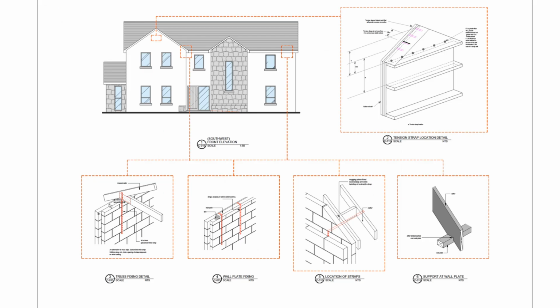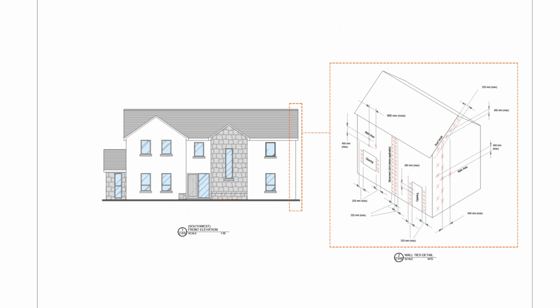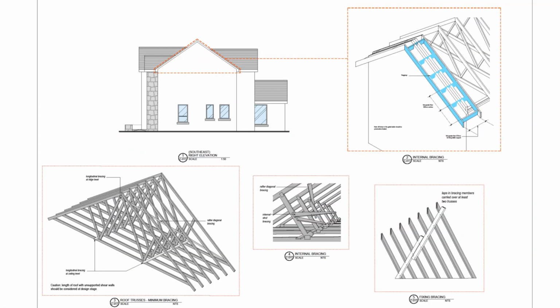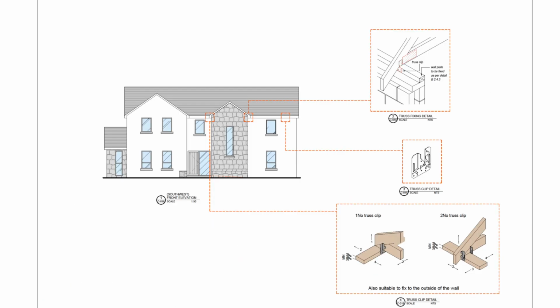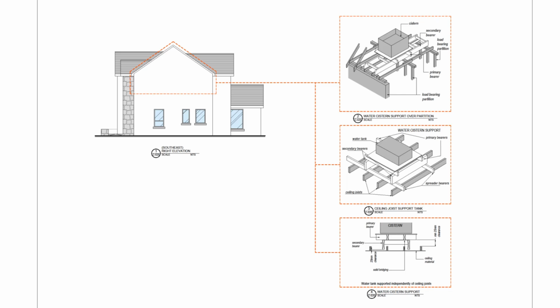Because in Ireland all of these details in the drawings are uploaded onto the BCMS system, particularly where the wall ties are at the openings. There's a double wall tie where the window and the cavity wall detail are, and external wall junctions. All this will be uploaded onto BCMS, and also given to the builder on site, to ensure that there is no ambiguity on the detail that is required.